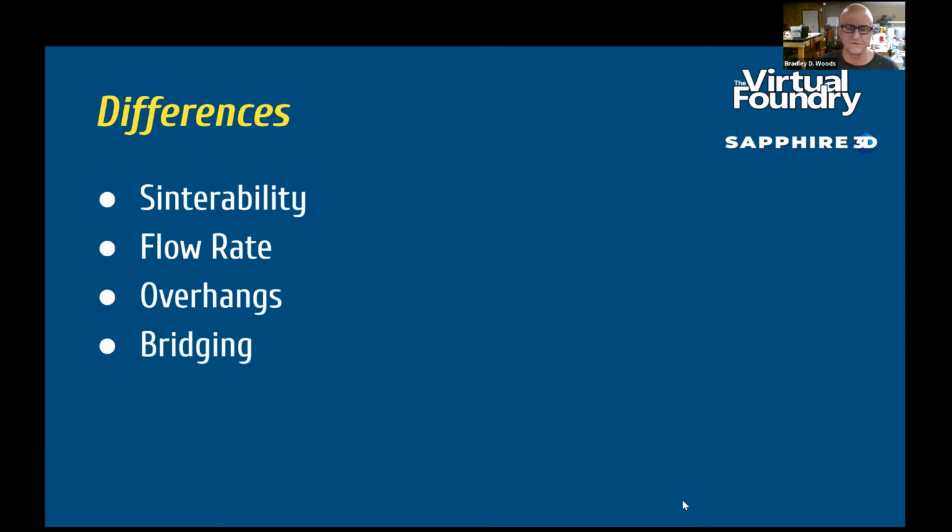And those points apply to bridging too. One thing about PLA is it will have a tendency to form a string when you're bridging between two different places. Filamet doesn't do that. Like I said, this goes back to the dough analogy. So bridging takes a couple tries.